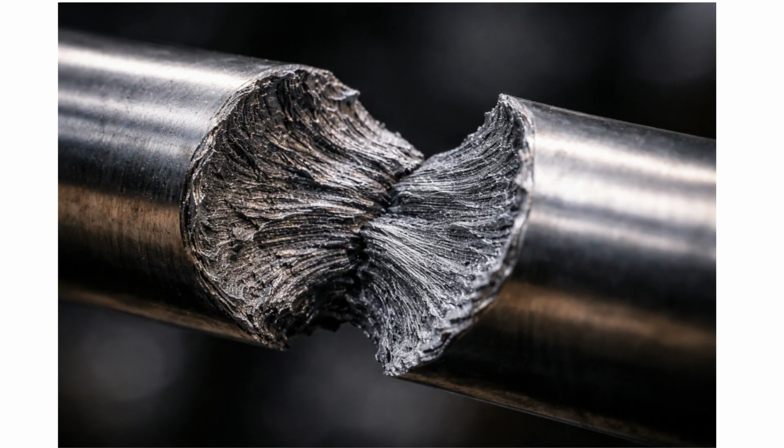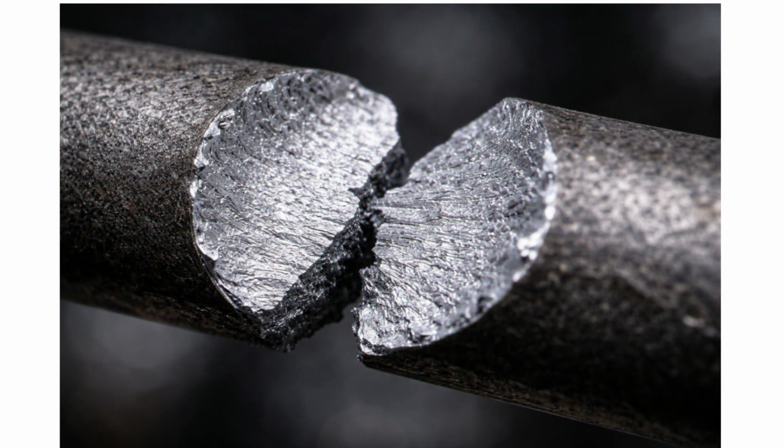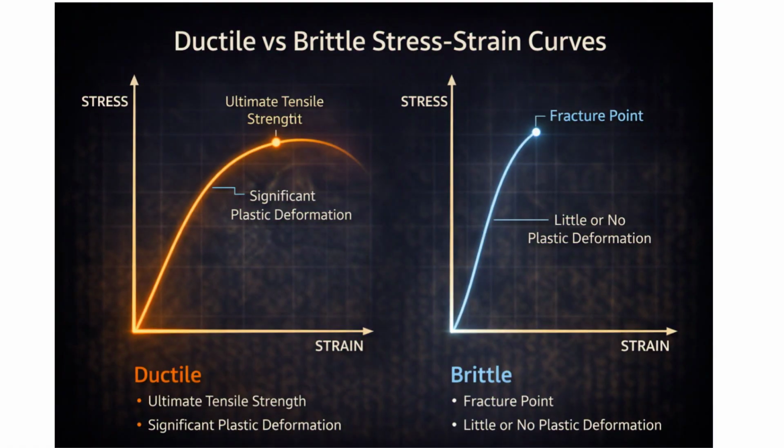Ductile materials show cup and cone fracture. Brittle materials break suddenly with almost no plastic deformation. Ductile materials like steel have long plastic regions. Brittle materials like cast iron fracture almost immediately after elastic limit. That's why brittle failure is extremely dangerous.